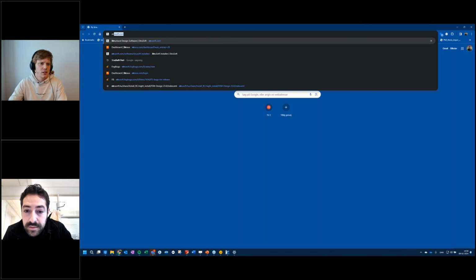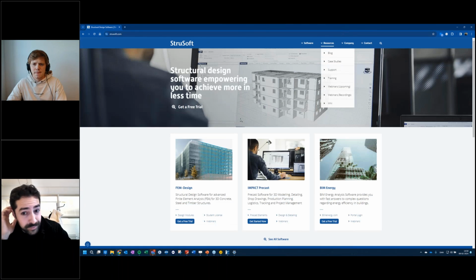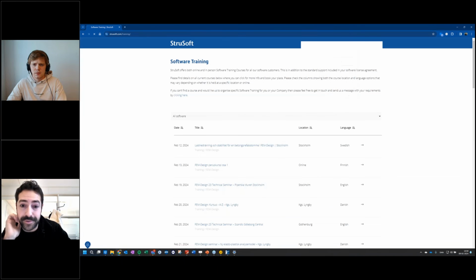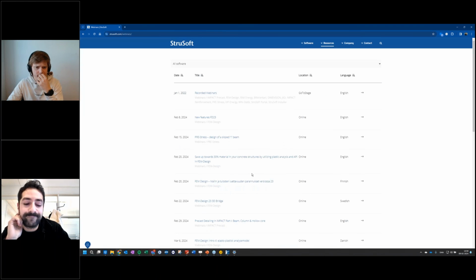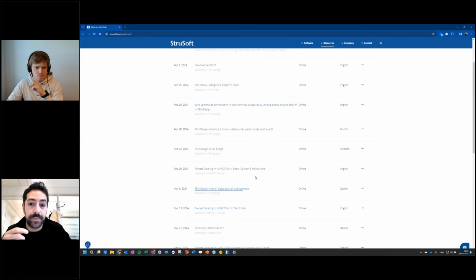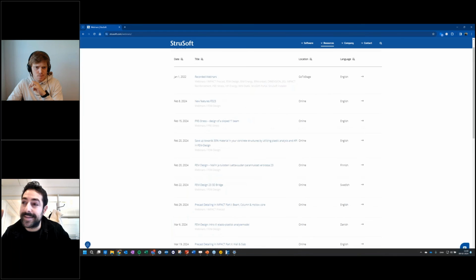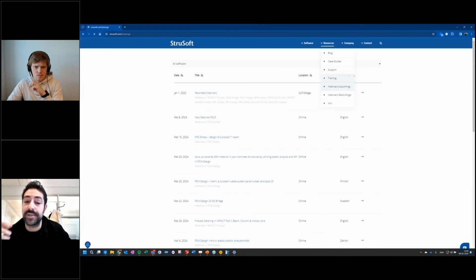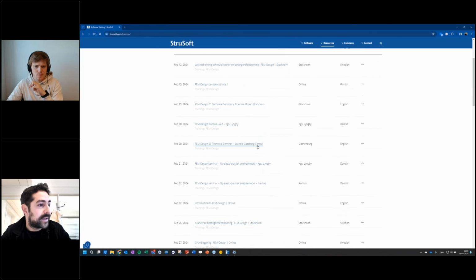Of course. And we also got a good question about virtual bar, if it was just the trimmed down version of the concealed bar. And not really, because in concealed bar you could only choose one object. So if you were having a T section, it was not possible. So in virtual bar you can choose several objects. So if you're creating, for example, a shell object in let's say a T-beam, then you can get the bending moment and the normal forces in it.